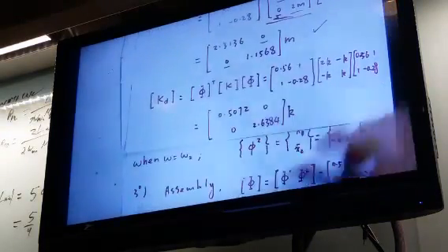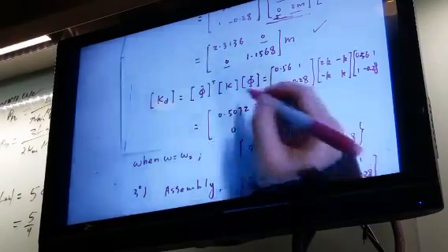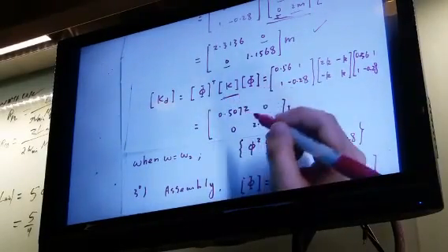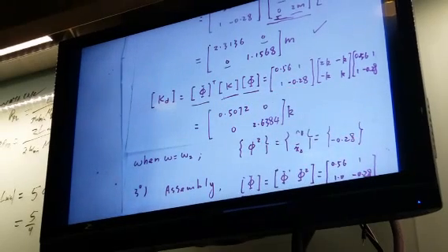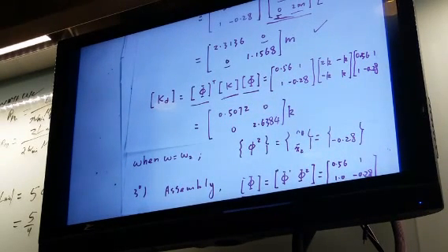We can do the same thing for the K matrix. This K is the stiffness matrix in Cartesian coordinate. This is the eigenvector matrix transpose. When you look at the original K, you have non-zero here and non-zero here. That is why those two unknowns will be coupled, because you have non-zero on the non-diagonal term. If you put in this transformation, you can get 0, 0 here. You only have non-zero numbers along the diagonal.